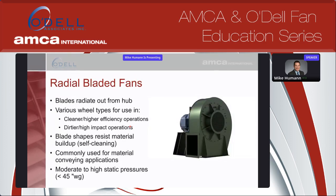First, we have radial bladed fans. A couple characteristics here. The blade radiates out from the hub. We'll show a little bit better picture of that in the next slide. But you can see here you have a very small inlet, and you have a small outlet relatively compared to the diameter of the wheel. You have options for cleaner, more efficient wheels, and you also have options for wheels that can handle dirtier, high impact operations. The blade shape does resist material buildup due to the radial design. Some people coin it self-cleaning, as it resists material sticking and clinging to it as it spins.